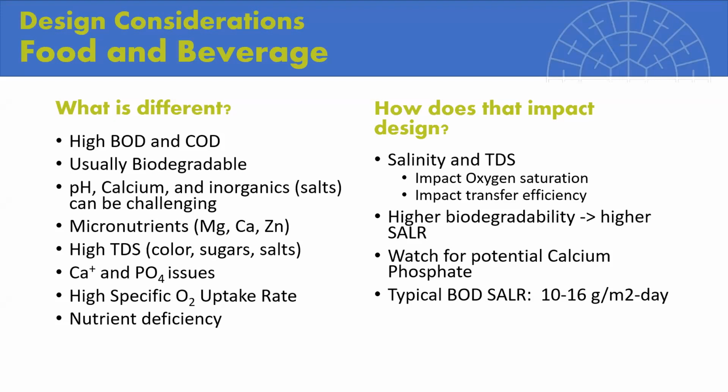With tube diffusers, that's not always the case. A lot of people prefer tubes because they have a lot of flexibility, high flow rate. They can get a very high density in the tank. However, with tubes, if they're not designed properly, the membrane of a tube system is not always fully activated.